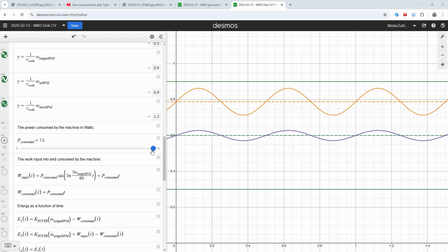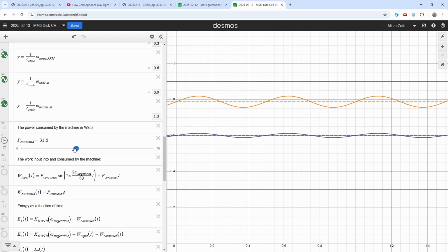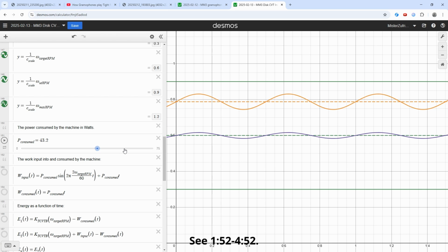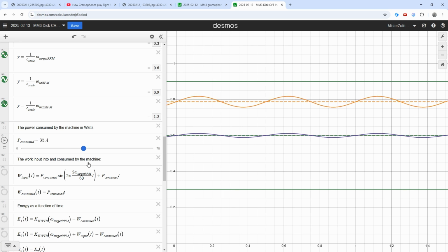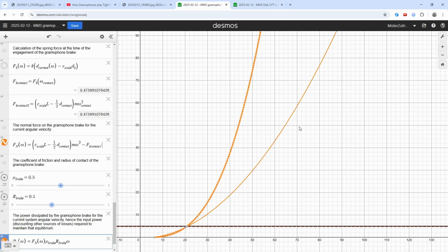The Huygens Drive can be simulated by reducing the energy fluctuations since those are being absorbed by the Huygens weight by a certain amount. See the earlier section of the video for details on why it isn't very good at doing that. Lower energy fluctuations means lower fluctuations in the driveshaft speed. Again, it is not practical to simulate the Gramophone Governor using this method.